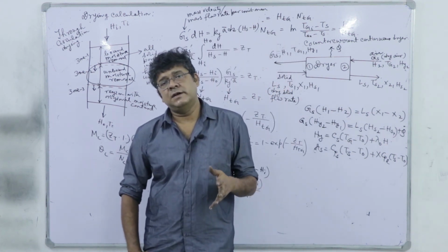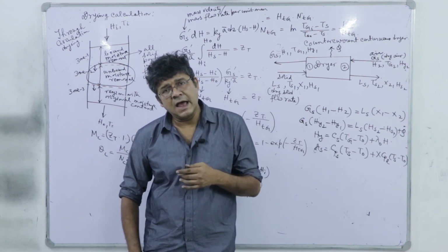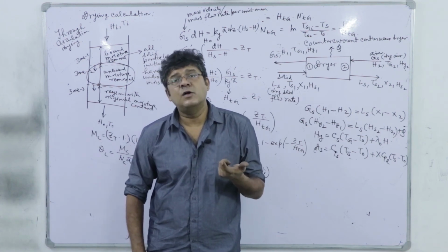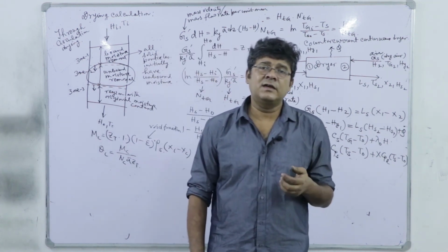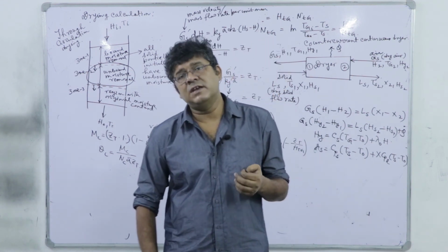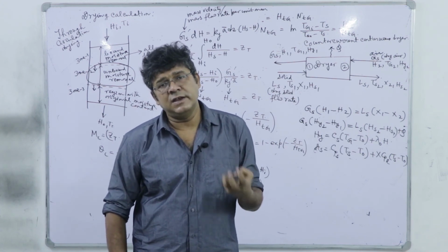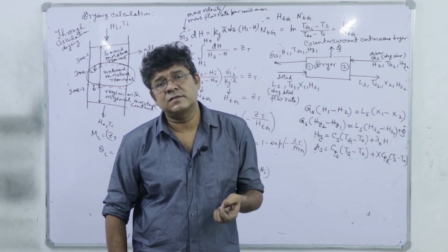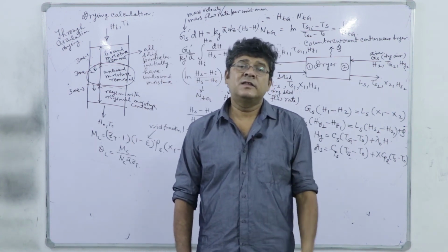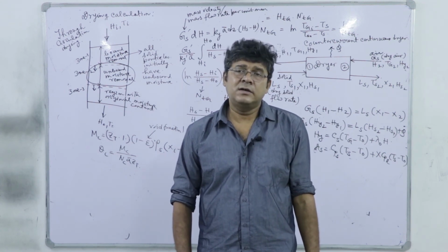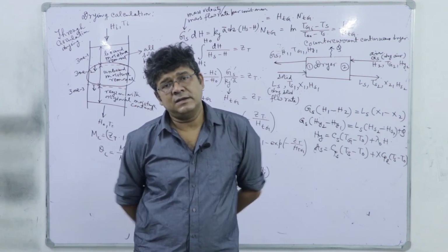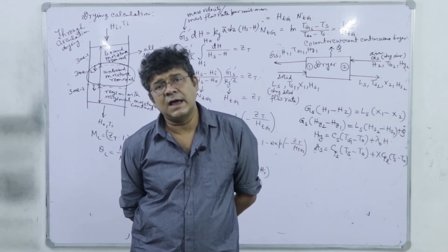So, we have considered the bed height design based on entirely the unbound moisture removal where the constant rate drying is feasible, right. So, for that we have used the material balance, and there we need this A bar data, which is a specific mass transfer surface area per unit volume of the bed, and from there we have predicted what will be the outlet humidity of this gas stream provided we know the height, this bed height or the tower height we know.